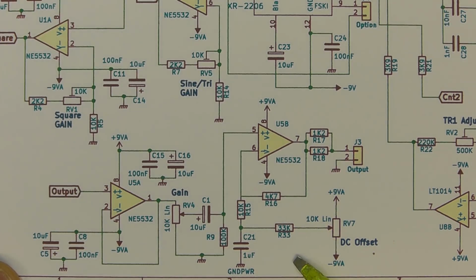Now what I'm also trying to do here, and I'm not 100% sure just how efficient this is, but we'll give it a try, is to add some DC offset voltage to the output amplifier so we can shift the level of the signal coming out on a DC voltage. All I've done here is, instead of taking the resistor R15 down to ground, I've taken it to ground through a 1 microfarad capacitor. This is not electrolytic, it's a normal 1 microfarad capacitor.